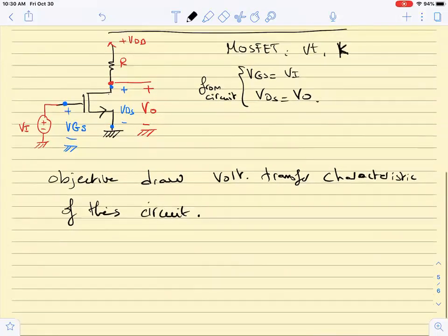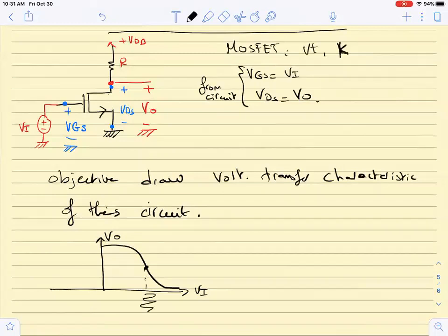What is the voltage transfer characteristic? If you recall from before, we were drawing VO versus Vn. What were these characteristics used for? For an amplifier. We would do biasing, and if we give a signal here, I'm going to get a bigger signal here. I am amplifying, and based on the slope I can know the gain. It is del VO by del VN at the bias point Q.